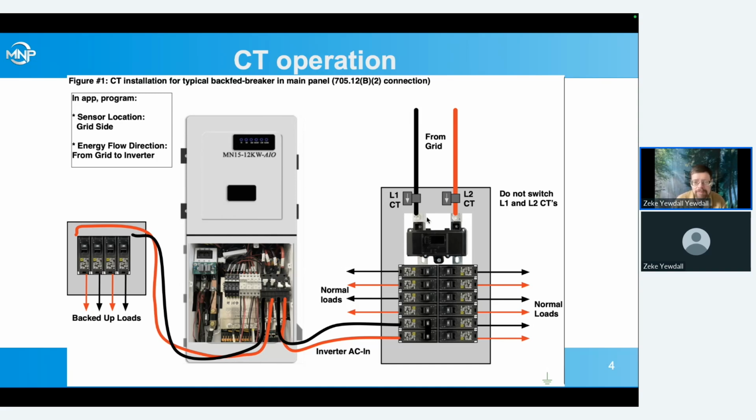And similarly, if we've got a limited export to the grid, where say maybe we've got a 6 kilowatt cap on what we can export to the grid because of feed lines or transformer sizing or something from the utility, we can limit the export to the grid to 6 kilowatts, and it will look at those CTs and adjust to do that. So those are the cases where we might be wanting to do something that really needs these CTs to tell the inverter what to do.